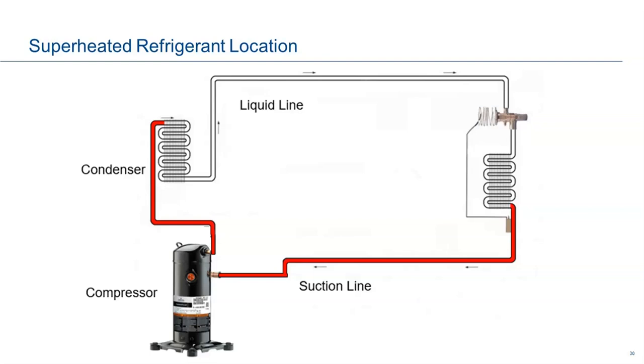Very, very important. Real quick, I'm going to do compressor fundamentals more than likely a few weeks down the road, but to calculate compression ratio, you're simply taking your pressure readings off of your gauges in PSIG, and you're adding atmospheric pressure, which is 14.7, but for easy math, we add 15, okay?